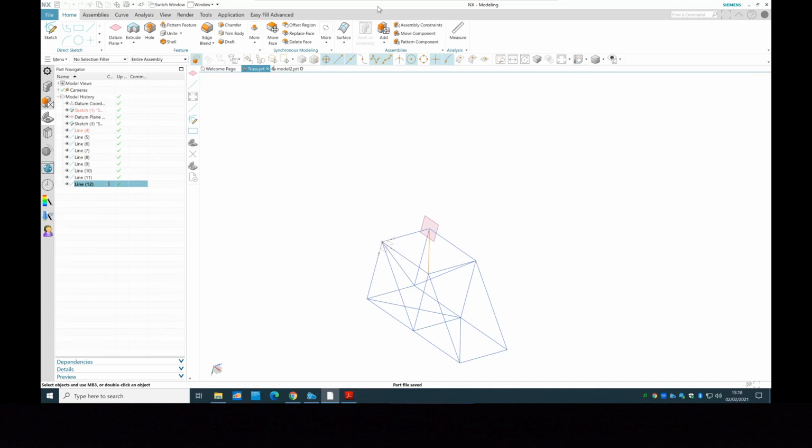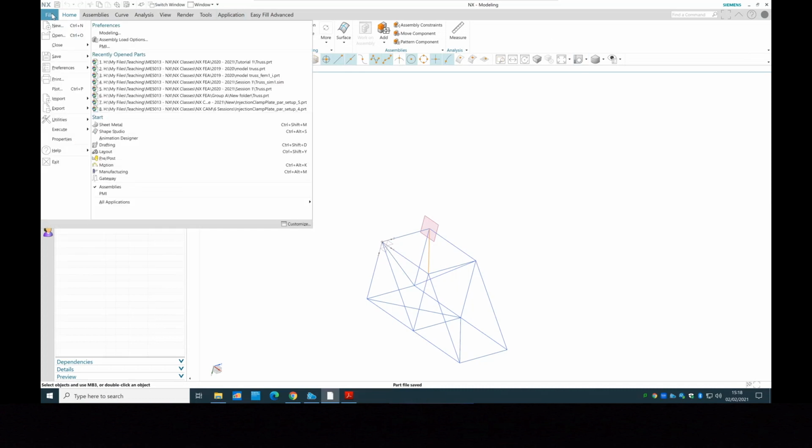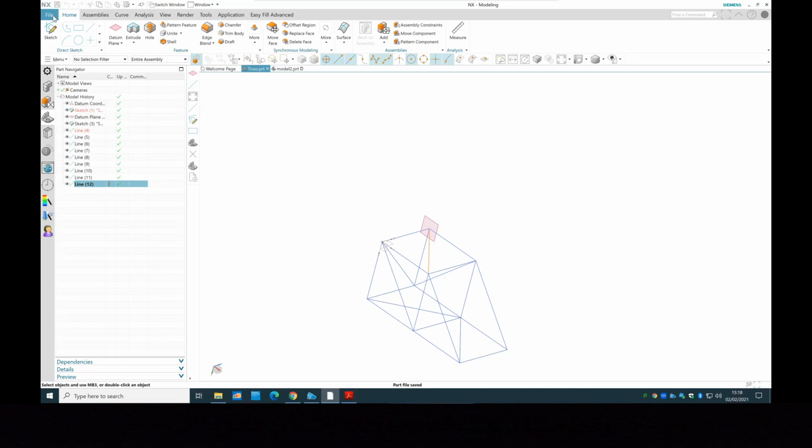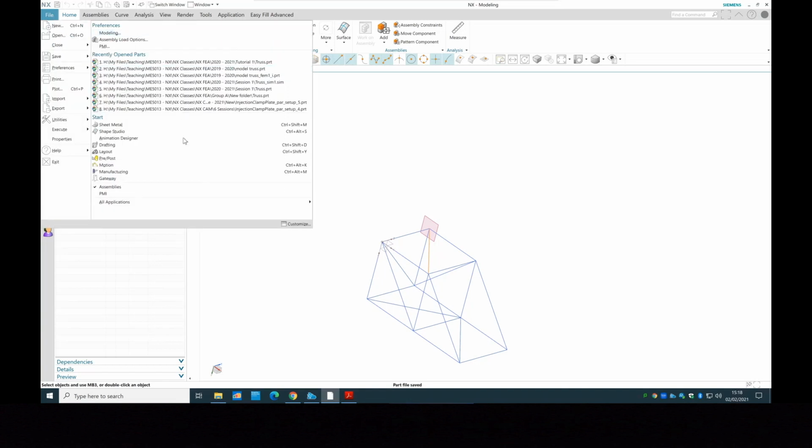In order to do it, go to the file, and in here, go to the different environment. NX calls it these days Pre and Post. It's basically pre-processing, post-processing, but that's the NX simulation. And you can see here, it says that it's the tools for finite elements modeling. So I will repeat it one more time. Click on the file. From here, go to the Pre and Post.